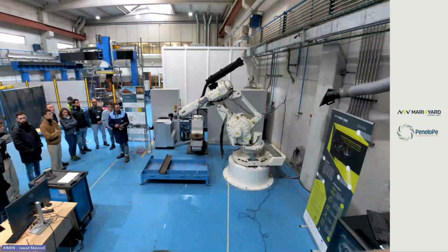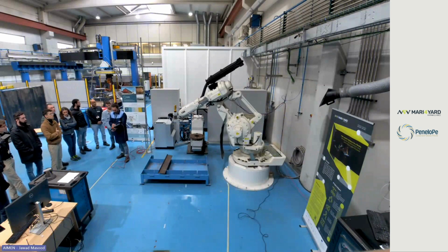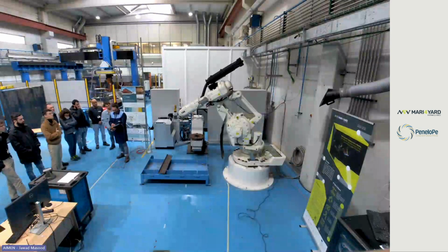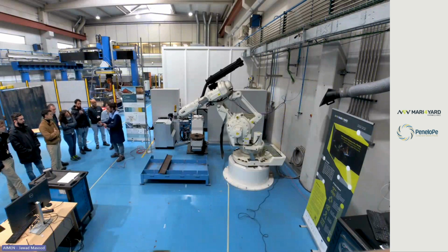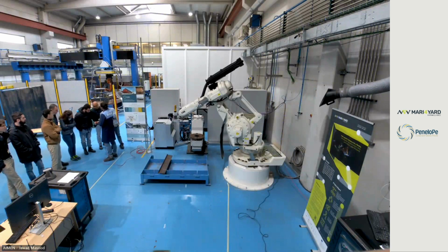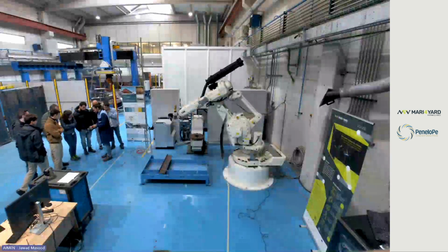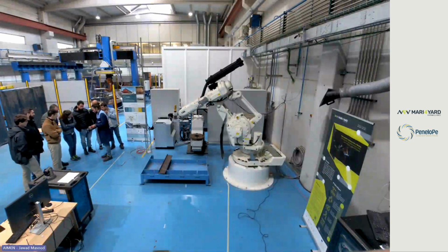This is going to be the second one. To do that, I have to add another move L instruction below with the name of square 20. Okay. I have to push here, modify position, to save the position.